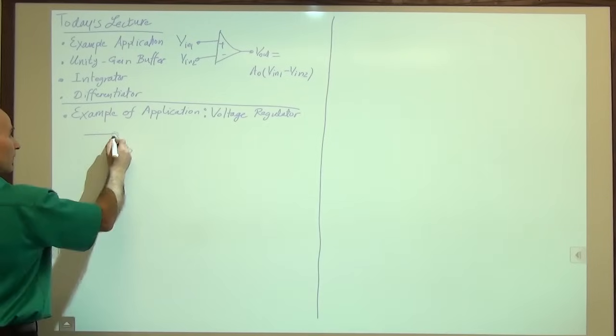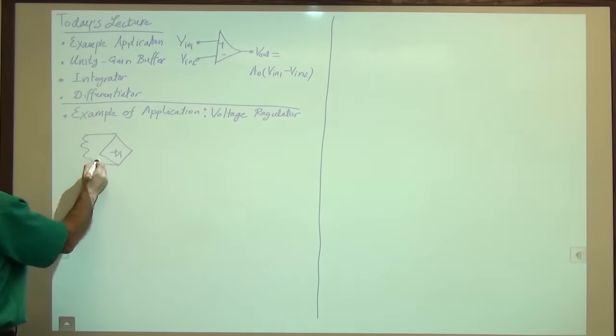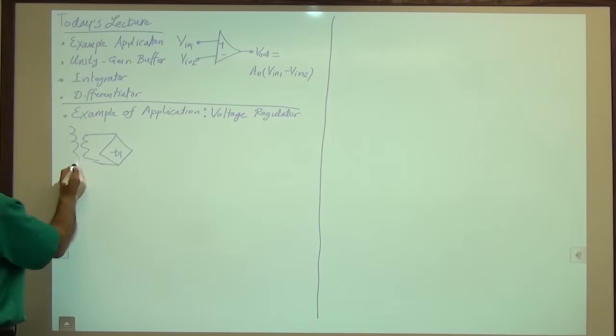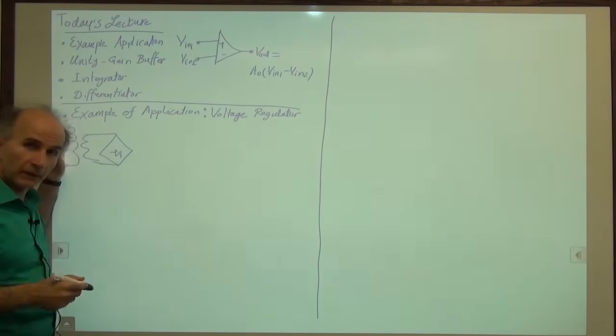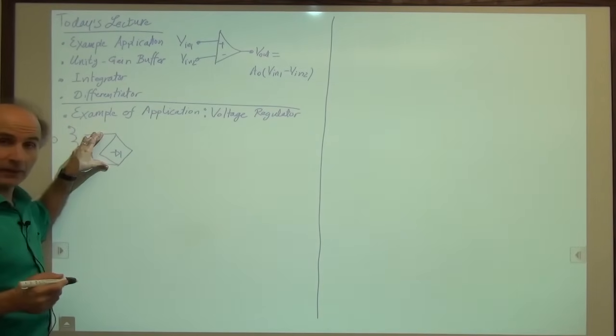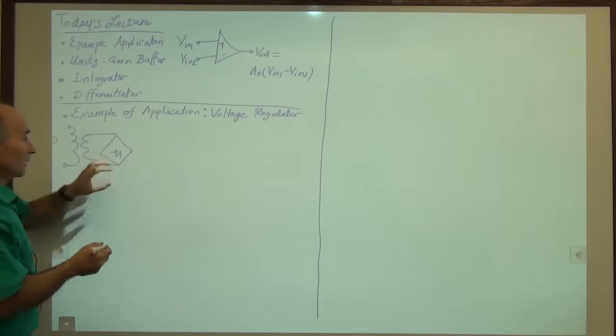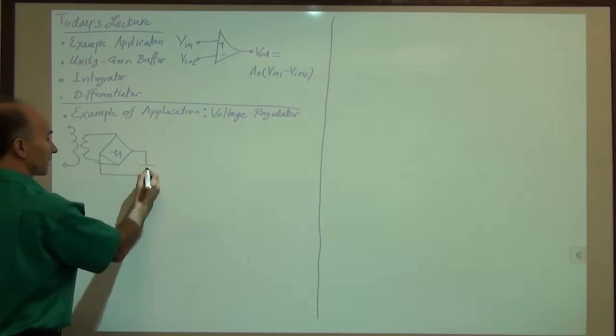We had, for example, a diode bridge. Before that we had a transformer. So at the primary of the transformer, we connected 110 volts or 220 volts. That gave us something here, maybe 20 volts. We rectified it, full wave rectified it, and gave it a capacitor.